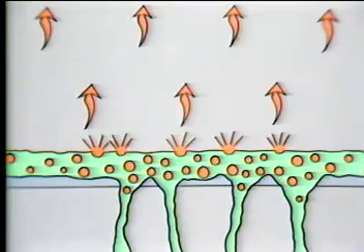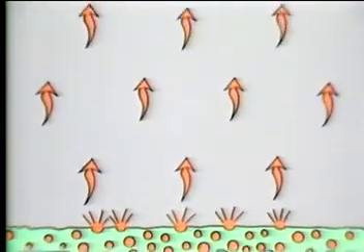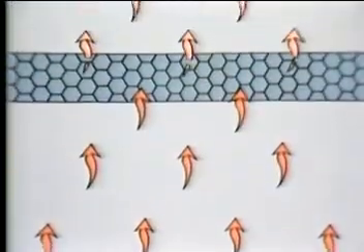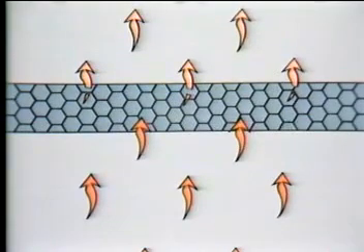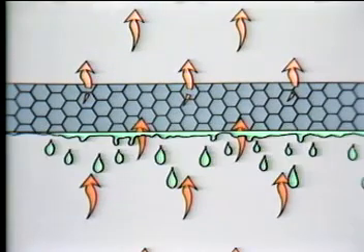The gas phase, which is directed to the upper portion of the vessel, is usually passed through a mist extractor to remove minute liquid droplets entrained in the gas. This one, for example, is made of knitted wire mesh. There are other methods used to perform the same operation.